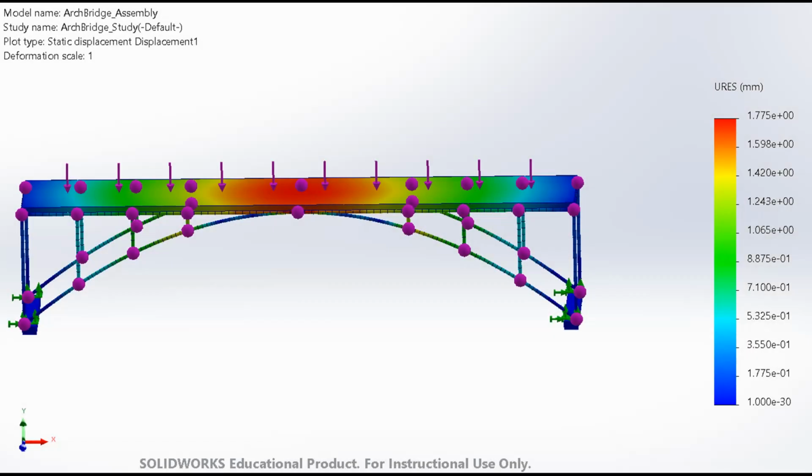To fix this, I replaced the rods with heavy square tubes, or put it differently, I made the structural members thicker. Of course, this solved the buckling and created the stiffest bridge of the group. This bridge deflected only 1.78 millimeters. But there was a trade-off.